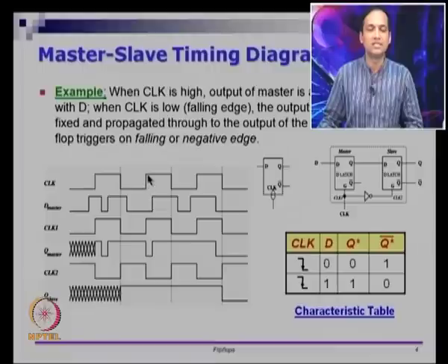Finally again this CLK comes on, which means CLK1 also comes on. When CLK comes on, at the positive level it starts with 0, goes to 1, then stays at 1 till the clock is on, right. So you will see that happening in Q also. It goes to 0 because when CLK1 came in, D master is 0, it starts with that, and then it goes to 1 at some point, stays at 1 till the clock goes off. So when CLK1 goes off, again there are changes here, it changes from 1 to 0 to 1. However, those changes are not seen in Q of the master.